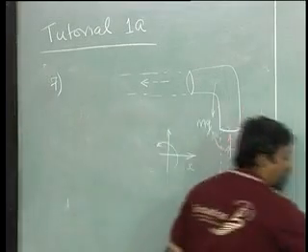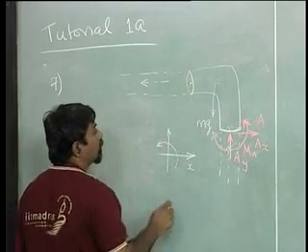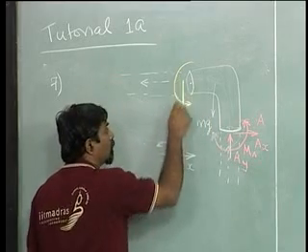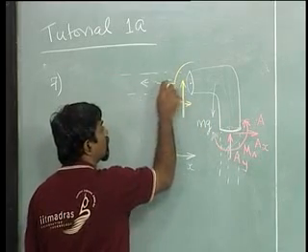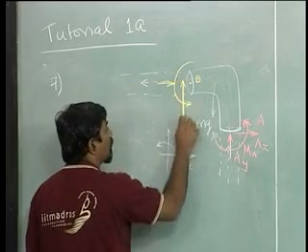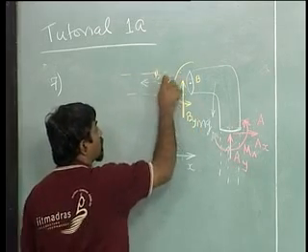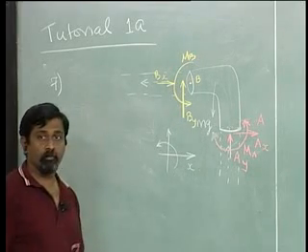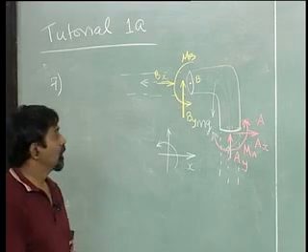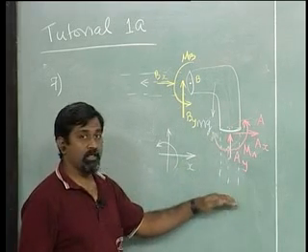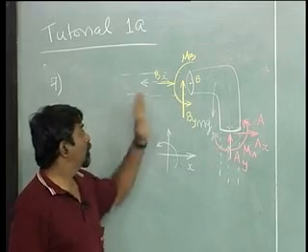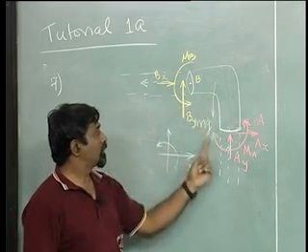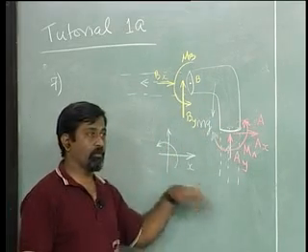Similar is the case if you take this particular point where I will have an interaction like this, which is similar to this, except let us say this point is B, I will have a By, Bx and M at B, where M at B is the couple acting on it. So, we have finished interaction with the pipe down below, we have finished interaction with the pipe to the left, we have finished interaction with respect to gravitational force. So, we have removed all those.